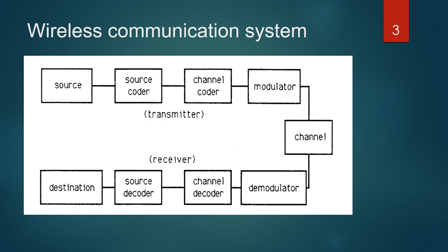The different parts of a wireless communication system consist majorly of a transmitter source which converts the information to a digital format, a source coder in order to remove the redundant data bits and compress it to the most efficient form of representation, a channel encoder in order to add extra parity bits to protect the bits from getting corrupted when subjected to noise, a digital modulation system which converts the binary data into waveforms, the communication medium, and the receiver system which decodes the received analog signal into the required data formats.